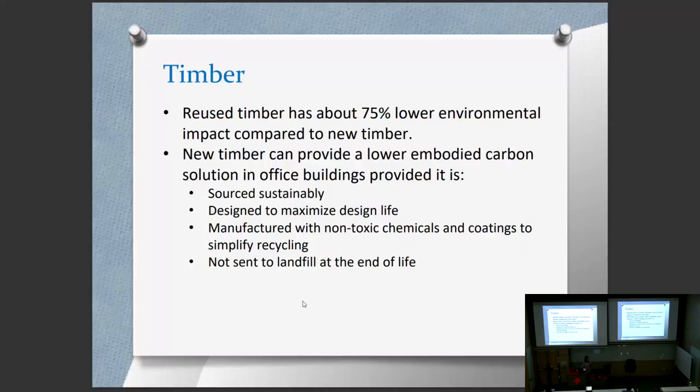So new timber can provide a lower embodied carbon solution in office buildings, provided that it is sourced sustainably, from sustainably maintained forests, designed to maximize design life. So we have to design the timber such that it can be used for many, many years. Otherwise the embodied carbon will still be large.